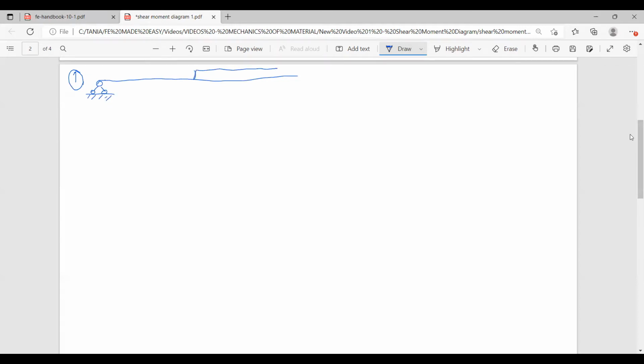Here we have a load, and here we have a roller, and this is going to be C. Reaction at C, this is reaction at B, and the horizontal reaction I will add just because this support has a horizontal reaction, but in this case it's 0 because we don't have any horizontal loads. This is 4 and this is 4 feet, and the load over here is 5 kilonewtons per foot. Okay, so let's solve for the reactions.